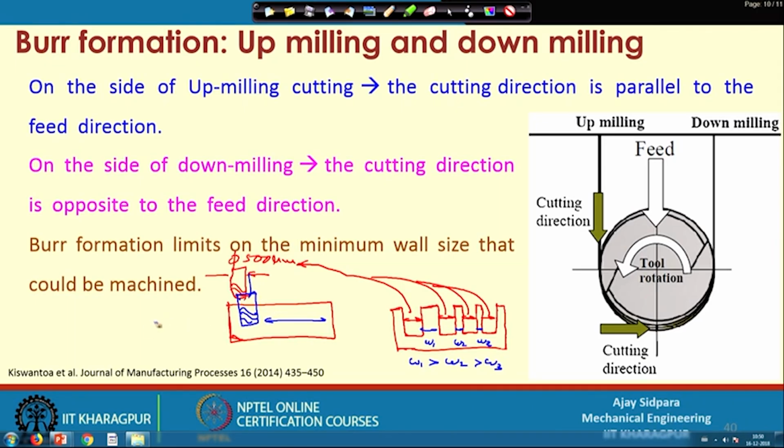So, material resistance will be very high, or it will support the cutting tool forces. Now, if you see from the vertical direction, this is your cutting tool, and the cutting tool will be rotating in this direction. This is your rotation direction, and now consider this is your workpiece. Then you will encounter two different types of forces. This is the normal force and this is the tangential force. So, this force is Fn, and because of these two different forces you will get material removal from the surface.